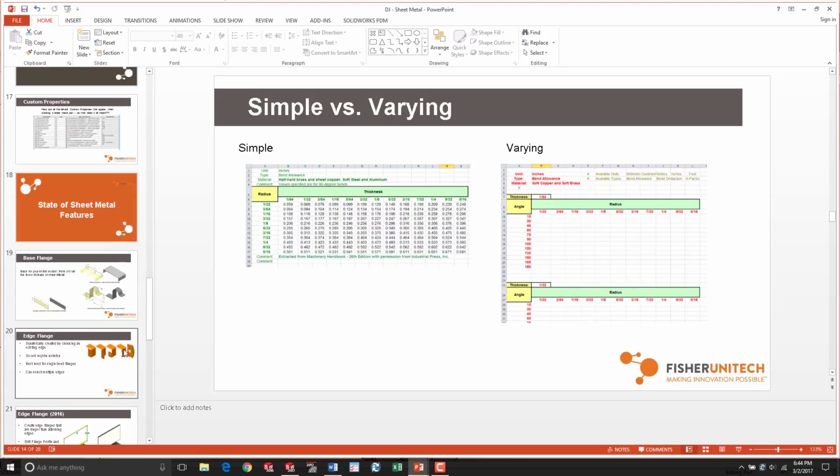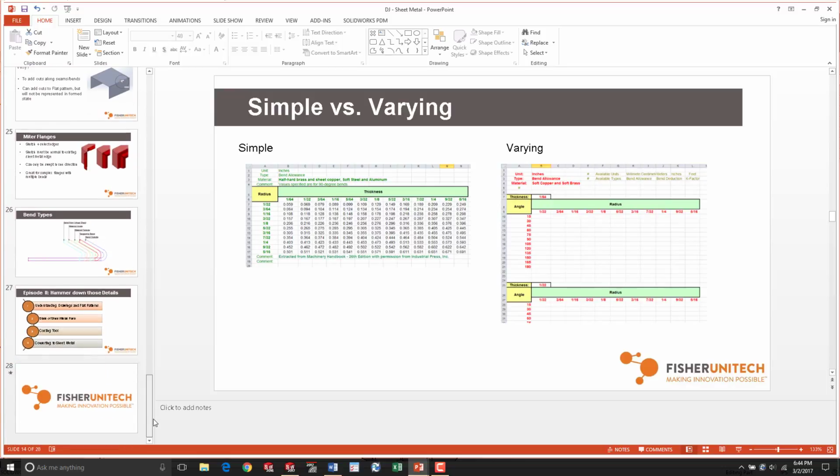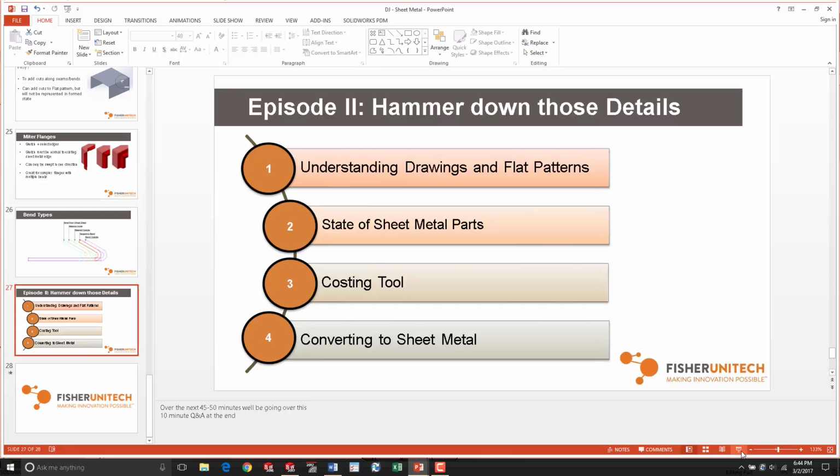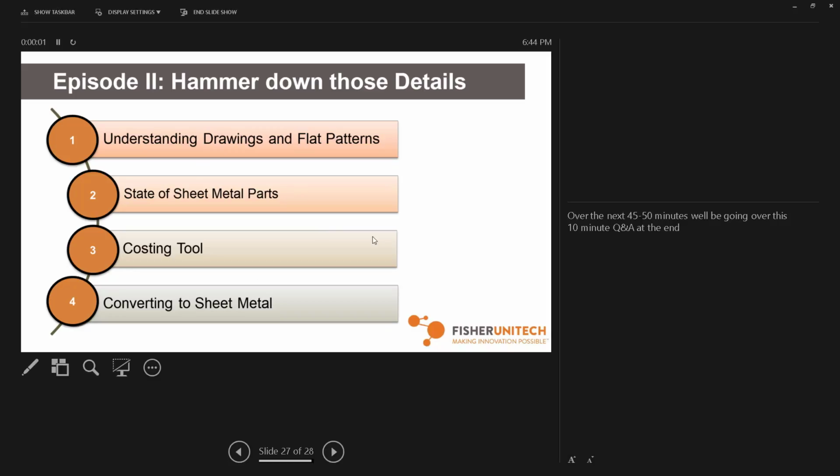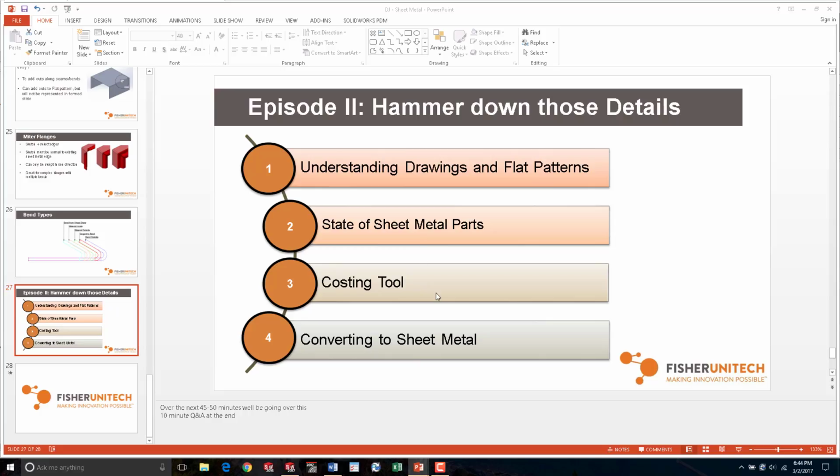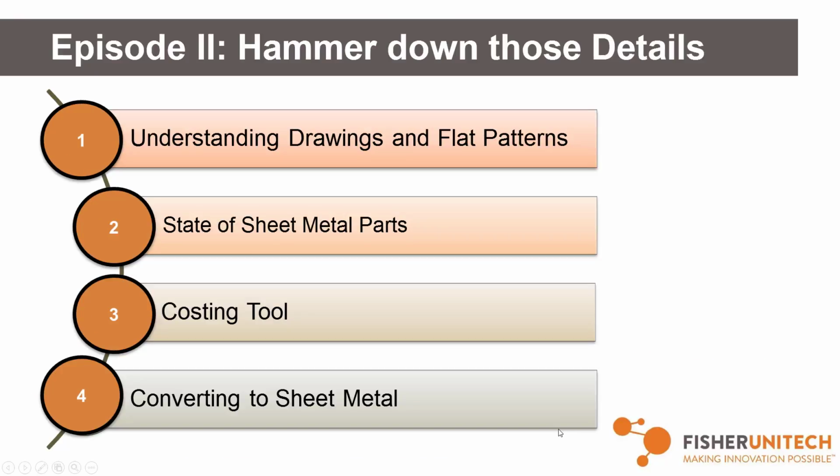We handle that by using different radiuses for different gauge. Correct. So we're using like the K factor .025, but then we're using different radiuses for different gauges. Oh, I see what you're saying. So if you're going from 12 to 7, you're changing your radius to keep it constant. The particular person that I deal with likes to use... Someone says I want you to supply everything. Wow. Okay. Cool.